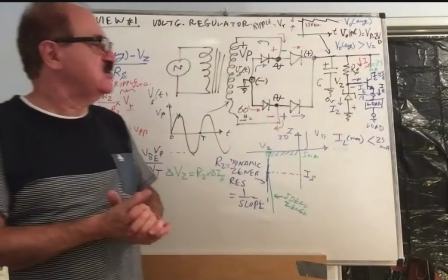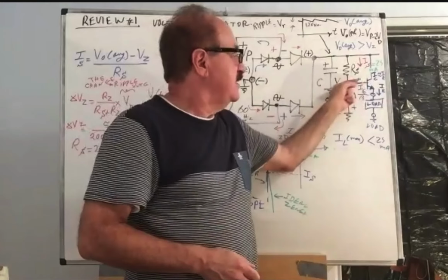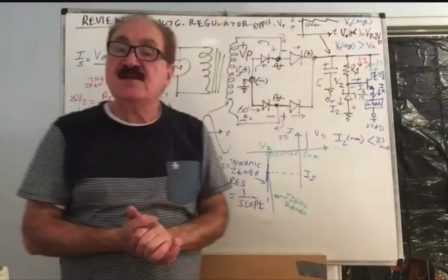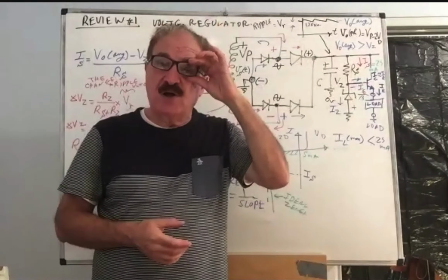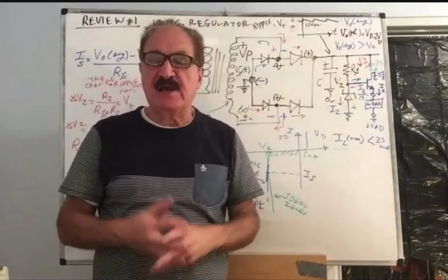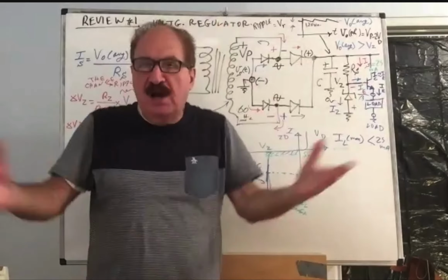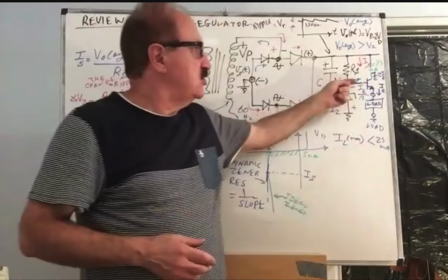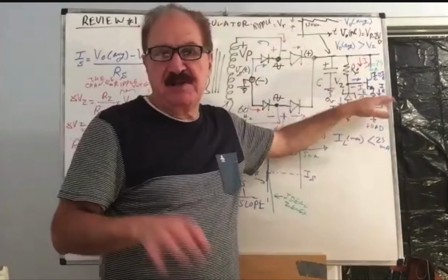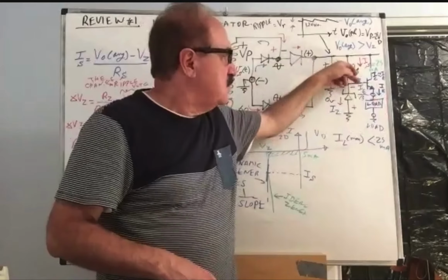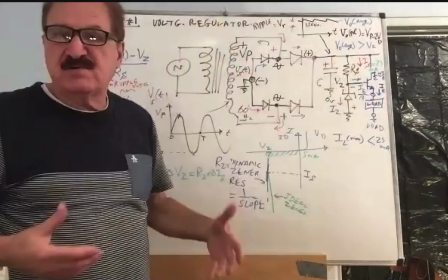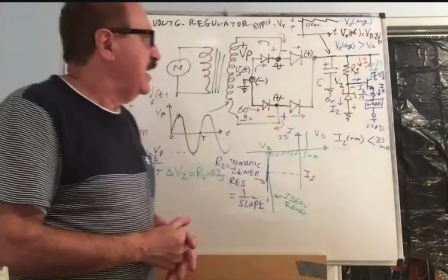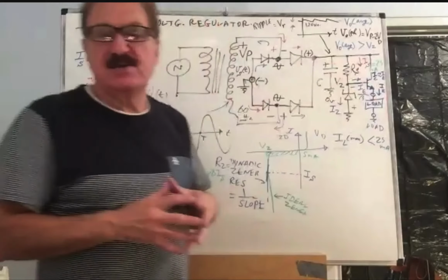So the bottom line is, it is the base current that is facing the Zener, and it can be made pretty small, especially if you select a high beta transistor. The higher it is, the better regulator it's going to be, obviously, because the current will be small. The change will be 100-fold, 150, maybe 250-fold smaller. And it will give you a nicely regulated Zener.